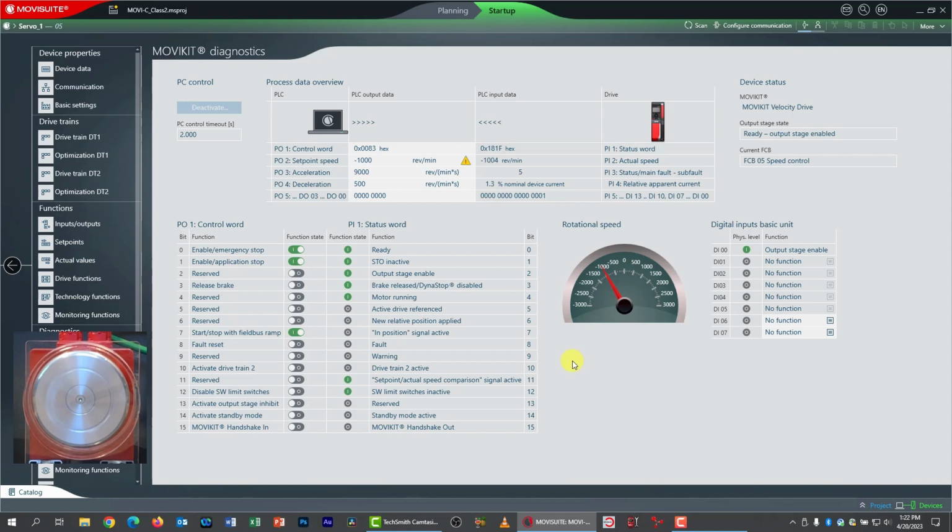Pretty nice. I've already pointed out that we can read the inputs and control the outputs over the field bus, and you can see my inputs. Let me just flip a few switches on my box and you'll see those bits changing here in PI5. Let me do that. I've just turned on all 8 switches on my control box, and you can see all those bits went to 1. So my PLC could take advantage of that if it cared. Okay, I'll take those away.